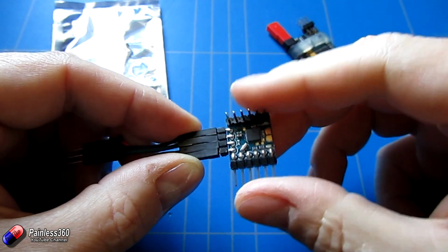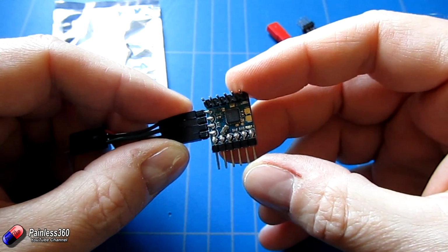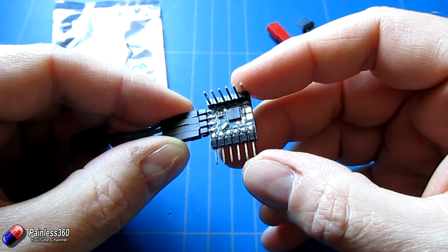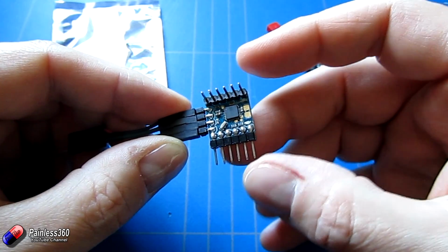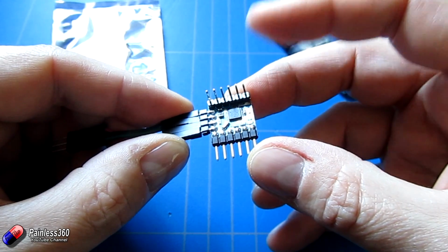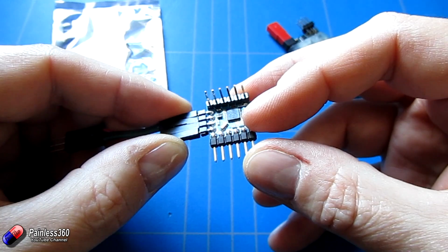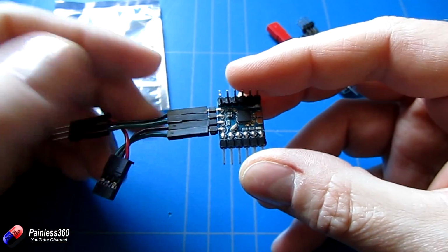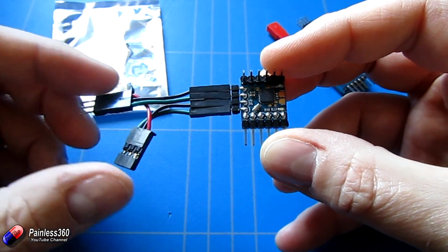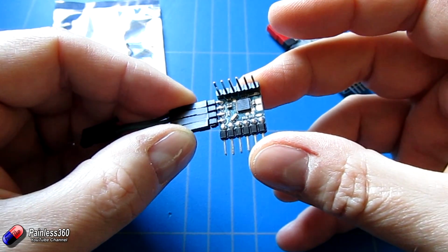Now, to make these things work you have to have very specific software that's set up for not only the board that you're about to talk to, but sometimes the version of the software that's running on it as well. And it's just the same with this, so we're going to have to do a couple of things to get this board working. We're going to have to install the fonts that are for the on-screen display, we're going to have to install the on-screen display itself, and then we're going to have to connect the board to the KISS flight controller as well as to our video transmitter and our camera so it can overlay the telemetry information on top of the image that the camera is seeing.